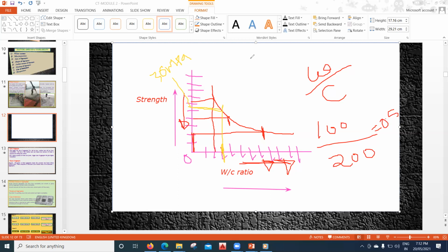Now let us say this is a site where you're working, and while doing the concreting in the slab, since you wanted more workability, you have started to add more water. So when you add more water, what is going to happen? Since water is the numerator, this 0.5 may go to 0.7 on the site, right? On the site I'm telling, because I've added more water. So if you're adding more water, the water cement ratio is going to increase.